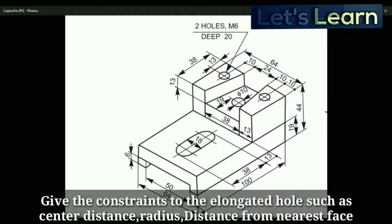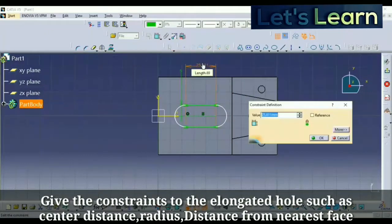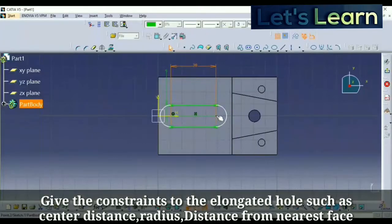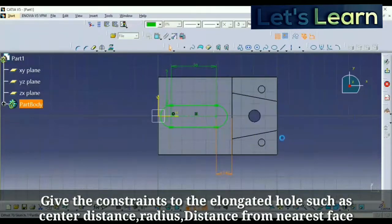I've changed the dimension, so center distance is 38. It's 38 now. It doesn't look good now. The distance from that corner to the point is 13 mm. Click on both points, click on constraint and give it 13.